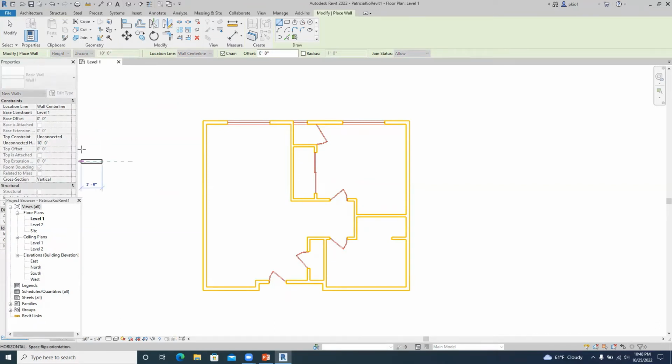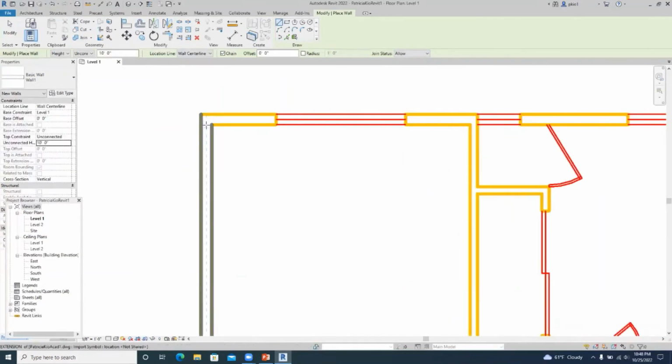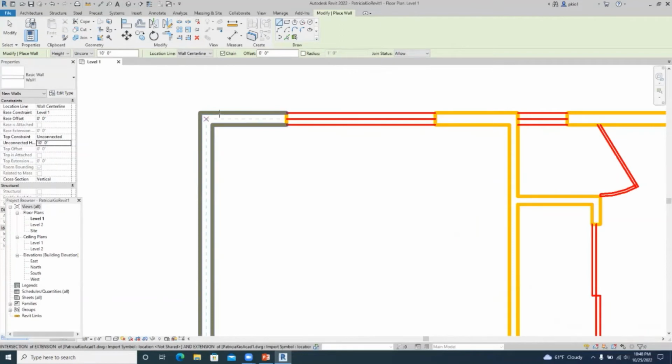Now we have our type of wall, so we need to start drawing. But before drawing, it asks where do we want to locate the wall, at the center. We do not have center drawings, but if you come over here, the center line will show too for us to pick it. In the example in class, I used the exterior, so let me stick to that one.